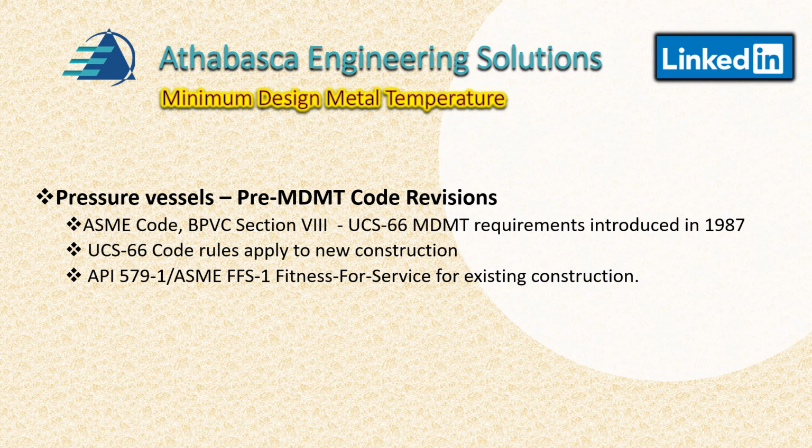Another limitation is that UCS applies to new construction only. So the remedy is to follow API 579, which has a part to evaluate the existing vessel. If you have a vessel older than 1987, that's a way of evaluating your component to see where your operating envelope is.